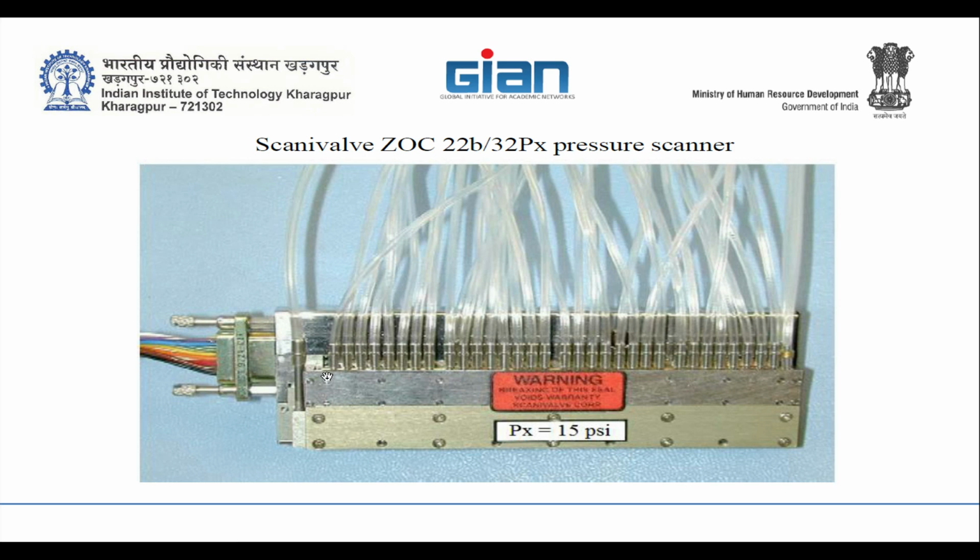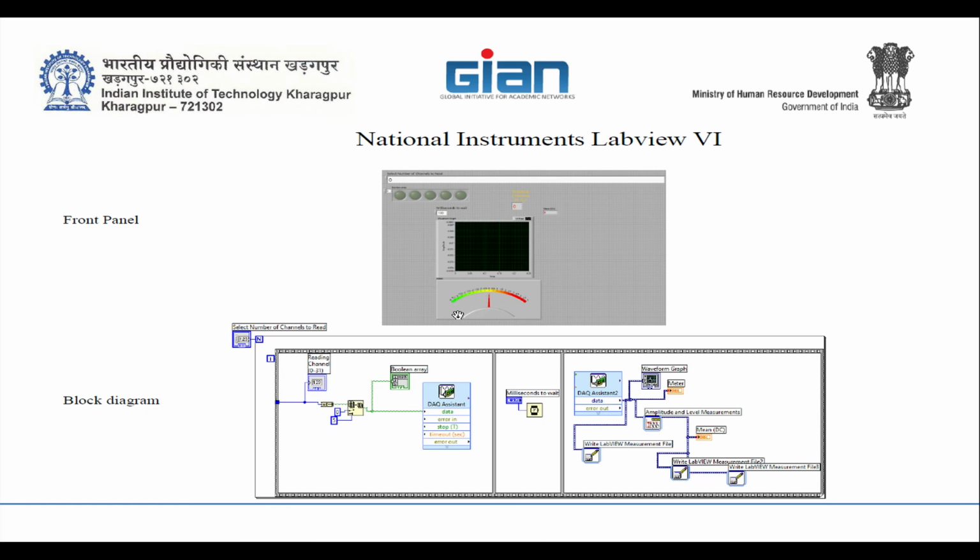With that you can calculate your pressure output, because the sensor gives you voltage, so you have to convert it with that sensitivity. Of course, there will be some deviation, which needs to be calibrated every 6 months or so, and that will be used for correction. And this is the LabVIEW VI that was used. This is the front panel, and this one is the block diagram.